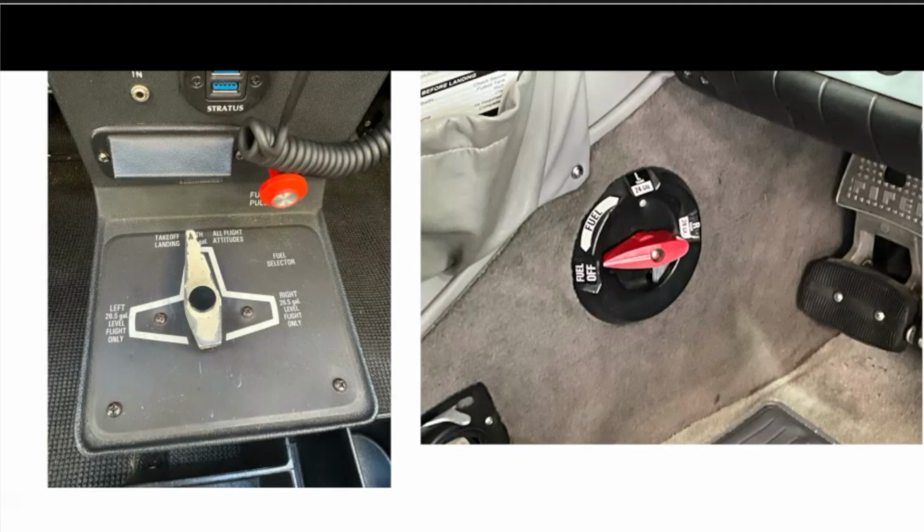The other thing too, when you're in this airplane, this is all in slides, and we're gonna blow right through here. We're talking through all the stuff. When you're in that low wing airplane, it's the fuel pump pushing that fuel. One thing we also want to do when we switch from left tank to right tank or vice versa is always turn on that auxiliary boost pump to make sure you've got fuel pressure.